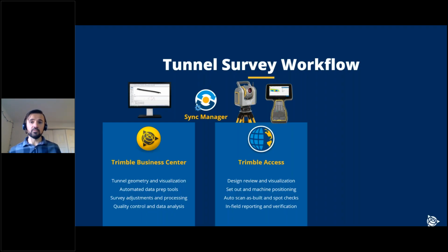One of the automated functions that I really like in Trimble Access Tunnels is the automated as-builting, where we take the tunnel design and automatically collect the as-built profiles based on the values that the user inputs. And then of course, in-field reporting is huge. So not only is it collecting data, but it's also having that real-time feedback while in the field. Has the data I've collected, if we built the tunnel in the right spot, is the overbreak significant? Is there underbreak, so we need to excavate more? That kind of feedback while I'm in the field.